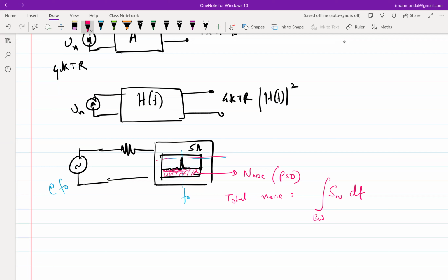Yes. Bandwidth, the signal that we'll be getting won't be just a tone, it will be a complete range of frequencies, right? So the bandwidth that we are talking about is that range. It will not be a tone, but if you are around 500 megahertz, and we say that I am taking out 1 kilohertz around 500 megahertz, that's equivalent to a tone. For all practical purposes, that is equivalent to a tone.